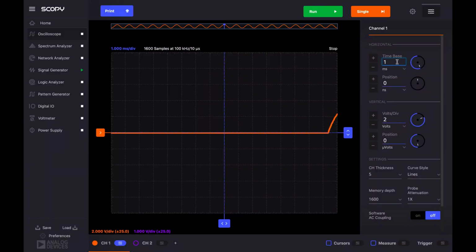So what I want to do is I'm going to zoom out. I can do that by entering a number, scrolling on the knob, or I can hit the plus button, and I'll do that. So basically what I've done is I've said, hey, look, instead of zooming in and taking a sample that quickly, I want to take readings over a longer period of time. I want to look at a longer period of time. So again, this thing is just a rolling capture log of voltage measurements. It's sitting there making these measurements, and it's saying, here's my history of them.